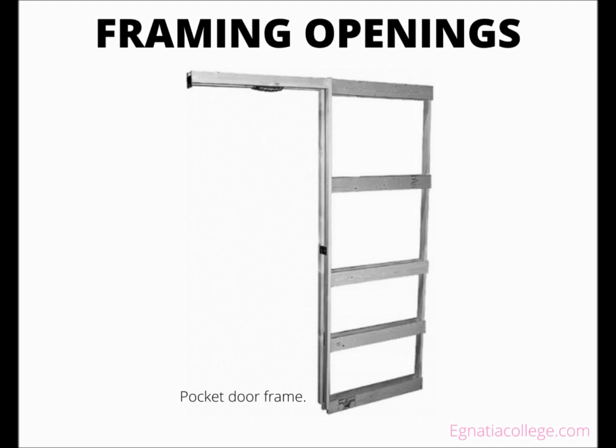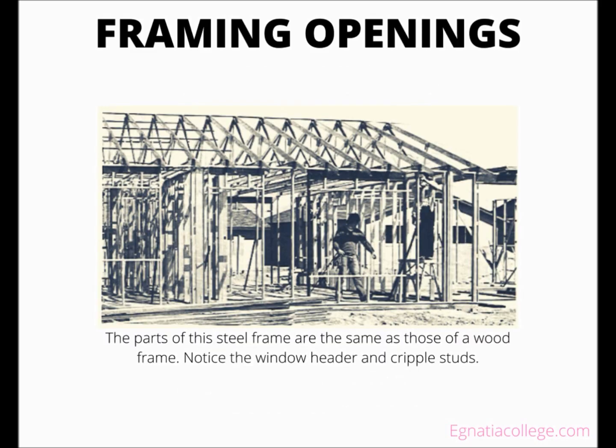Several systems of metal framing are available for light construction. The basic elements of light gauge metal framing are the same as for wood framing. These systems use top and bottom wall plates, studs, and floor joists. To make light gauge framing compatible with wood, the metal members are made in common sizes for wood framing.